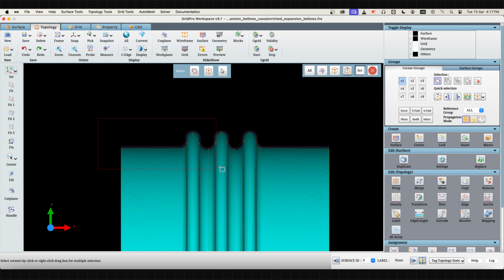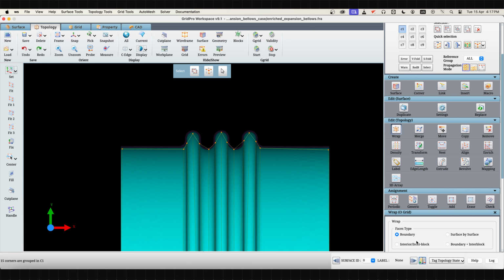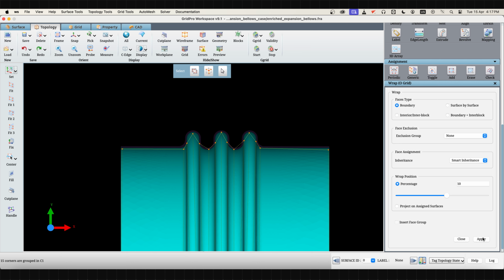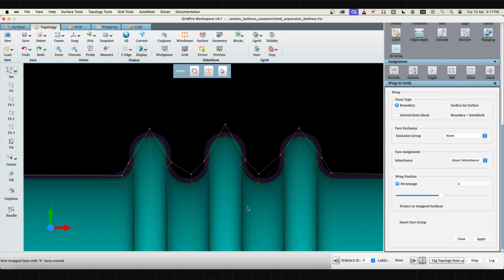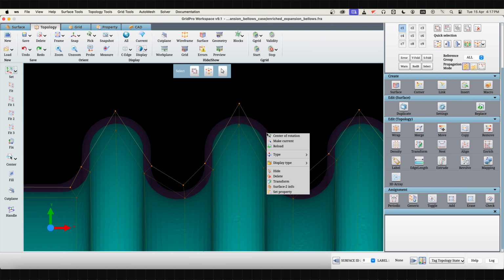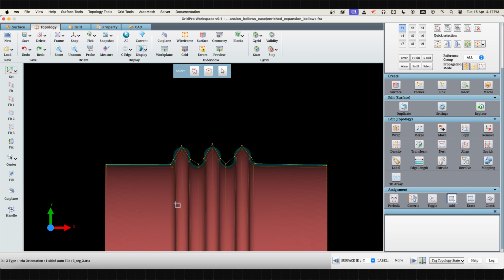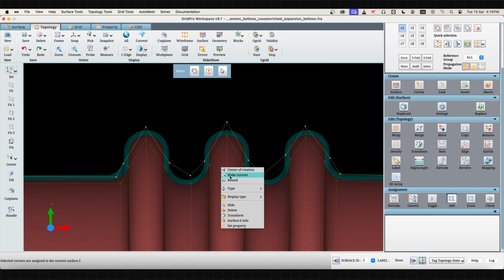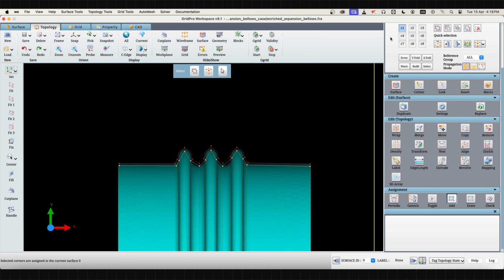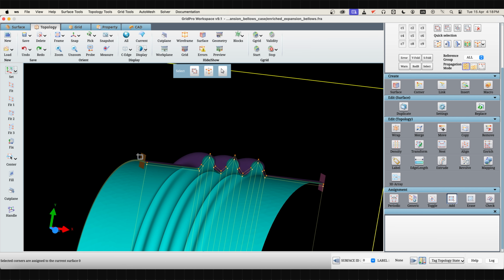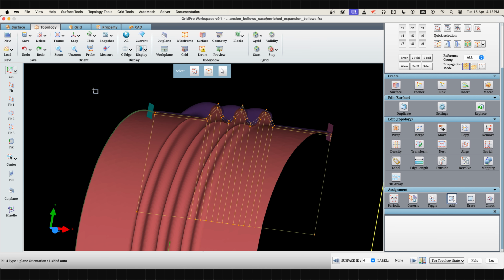Next, a boundary wrap is performed to copy the top layer of corners for the solid region. It is recommended to do the surface assignments on the 2D topology before rotating it to 360 degrees. This reduces manual effort by automatically carrying the surface assignments throughout the complete topology.